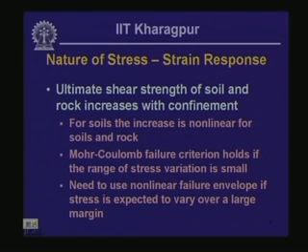That means, if you have the same type of rock occurring at great depth underneath the ground surface, as well as at another level near the ground surface, an identical deposit of rock, then the strength behavior that the deeper element is going to exhibit is going to be much larger compared to the strength of the shallower element.